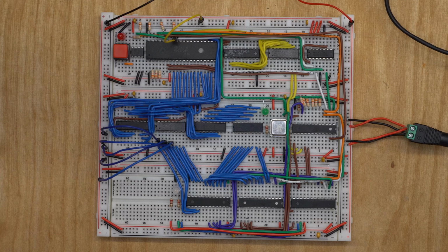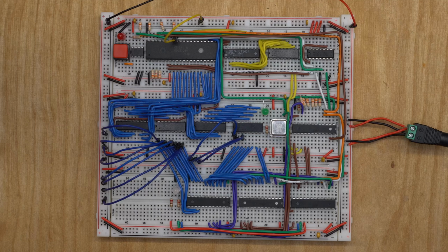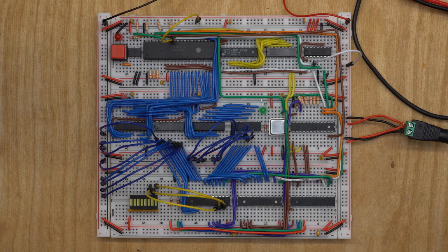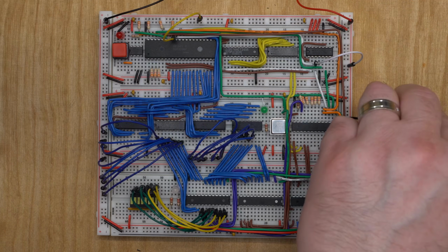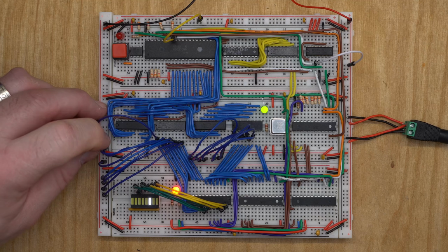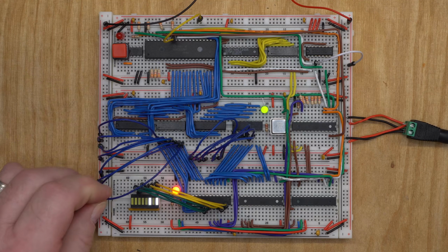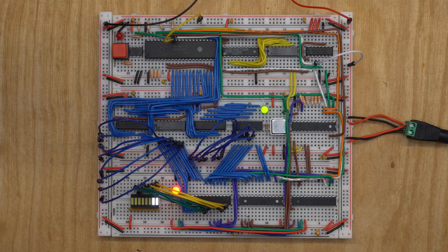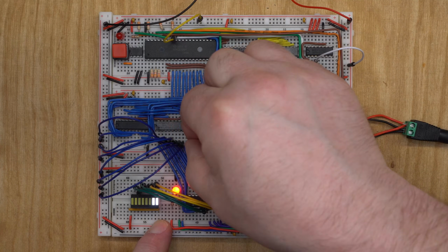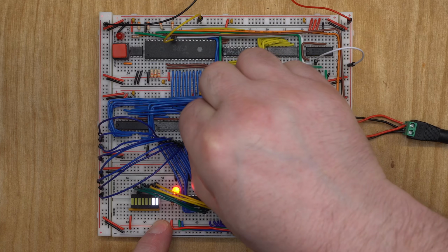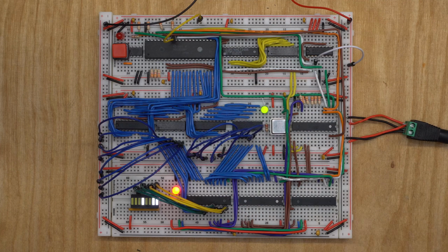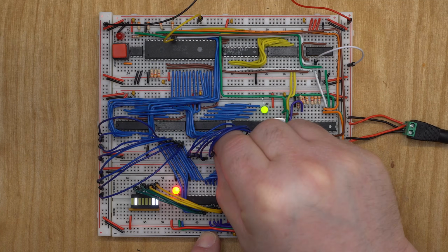Starting from the left, we've got the memory decode PLD. I added a small LED bar graph to make debugging less, theoretical. The three main regions behaved exactly as expected: constant block, I/O request, memory request. So far, so good. I then tested the 4 built-in I/O functions: ROM disable, speed select, IRQ, and FIRQ.